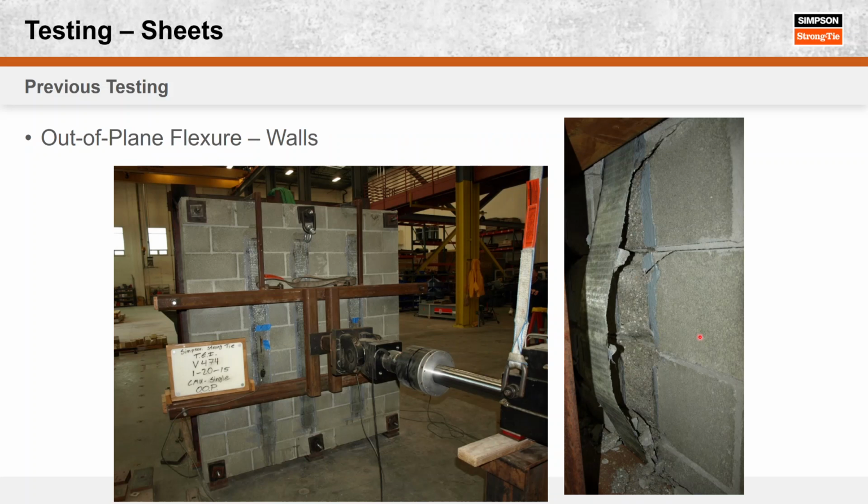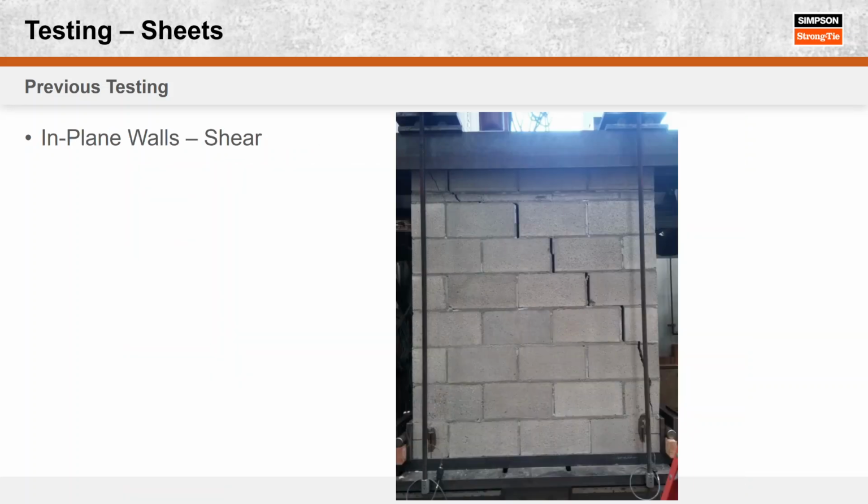So, out-of-plane flexure on walls with FRP. Just like the testing we did with FRCM, and this is the actuator that pushed and pulled. And there's a frame just like this. Actually, no, there's not. There's just a horizontal member on the back side of the wall that helps pull the wall back towards it. And so this shows a failure of a debonding strip that was bonded really well because it pulled chunks out of the CMU wall. I don't think I have loads on that one.